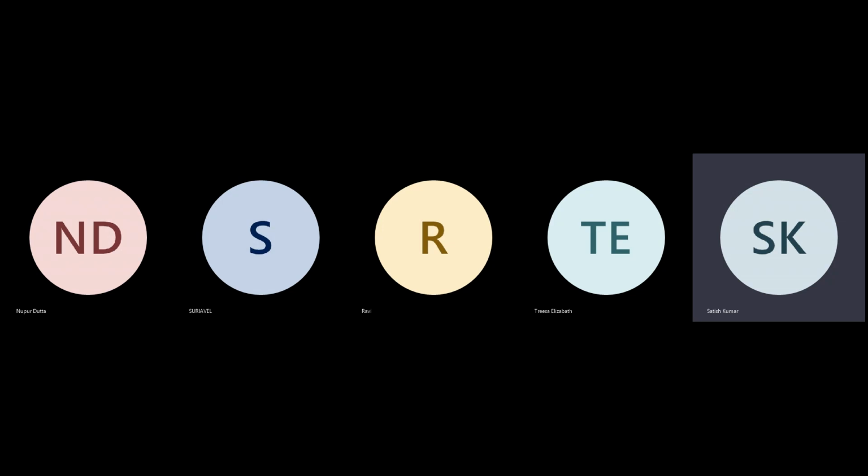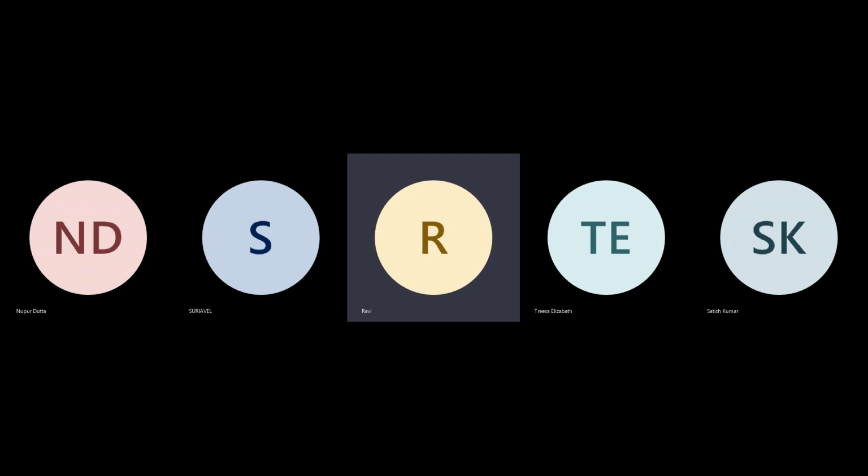We can make a map of color hierarchy for standard cells. You can create a Tcl file which says get cells of that pattern, whatever that module internally has, and once you have selected, you can set the color pattern. You can put an attribute, or you can use the GUI to set the color pattern.